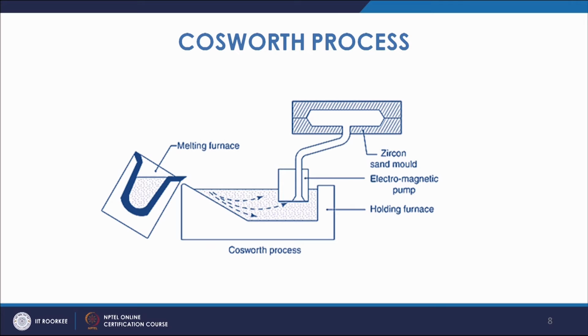So, this is the zircon sand mold which has quite a good conductivity, as compared to the silica sand or other sands. In that case it gets solidified and you get a clean kind of product.